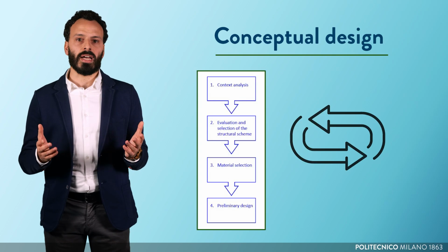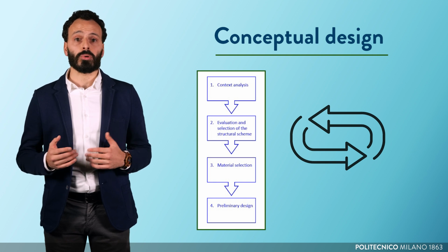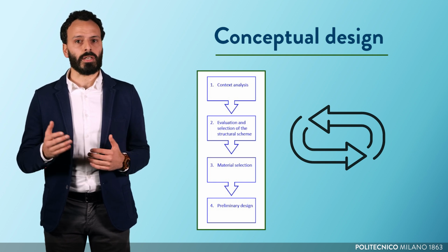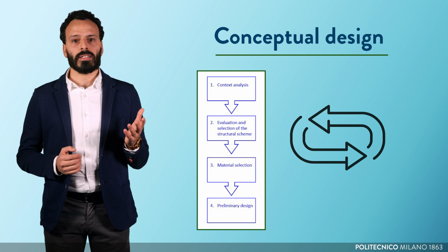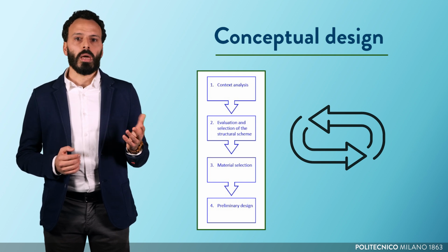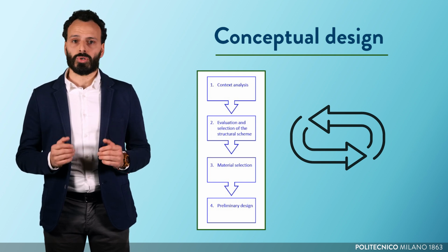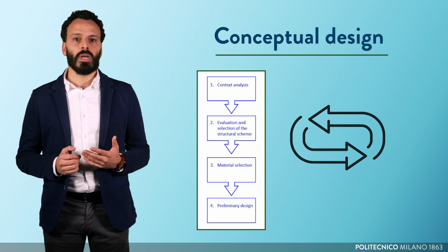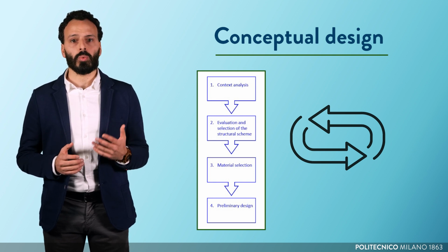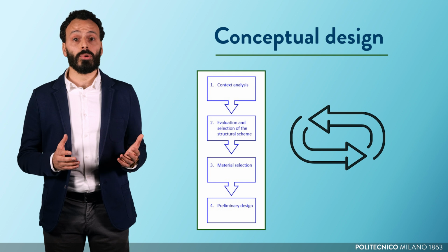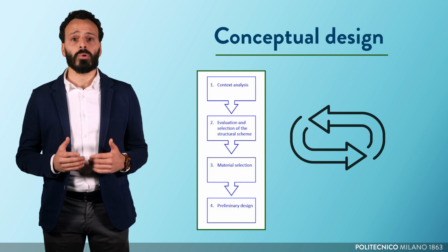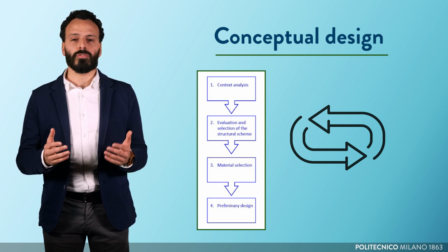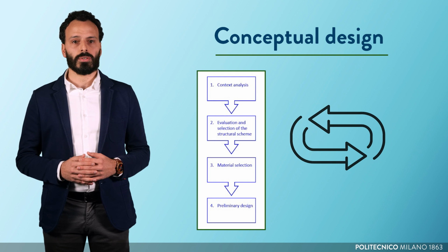In the conceptual design, it's not always necessary to proceed through the four steps in a strict order. Some constraints, such as material availability, may require a more adaptive approach. For example, if only certain materials are accessible, it may be essential to evaluate which structural schemes are feasible based solely on the available resources before moving forward with other design decisions.